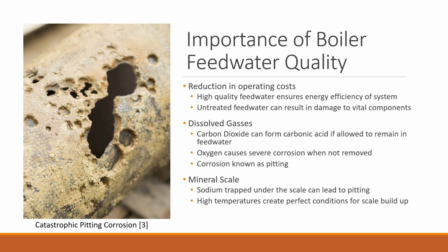Another concern is mineral scale. Mineral scale is built up when the water is not treated, and sodium trapped under the scale can lead to pitting. High temperatures are the perfect conditions for a scale to build up, and obviously this is pretty common in a boiler system, so it's something that you need to ensure you're removing prior to operation.